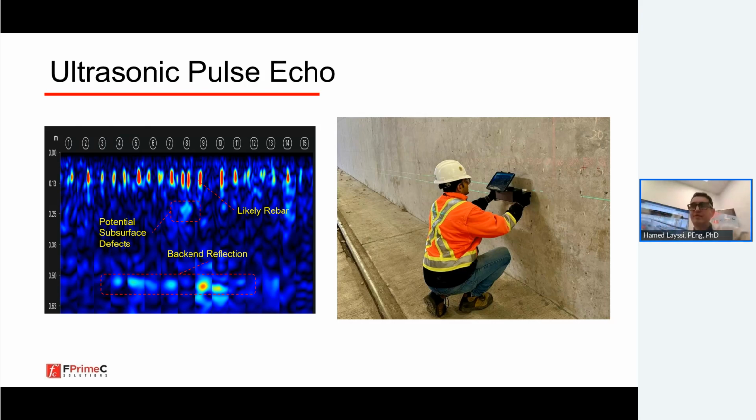And maybe in 5 square meters, this doesn't end up being a big difference. But imagine you're doing this on a 2-kilometer bridge, then this easily becomes a huge problem. So know the problem you're dealing with. This test helps identify potential delamination at a very early stage. So if there is any delamination, this test can basically help us identify it.